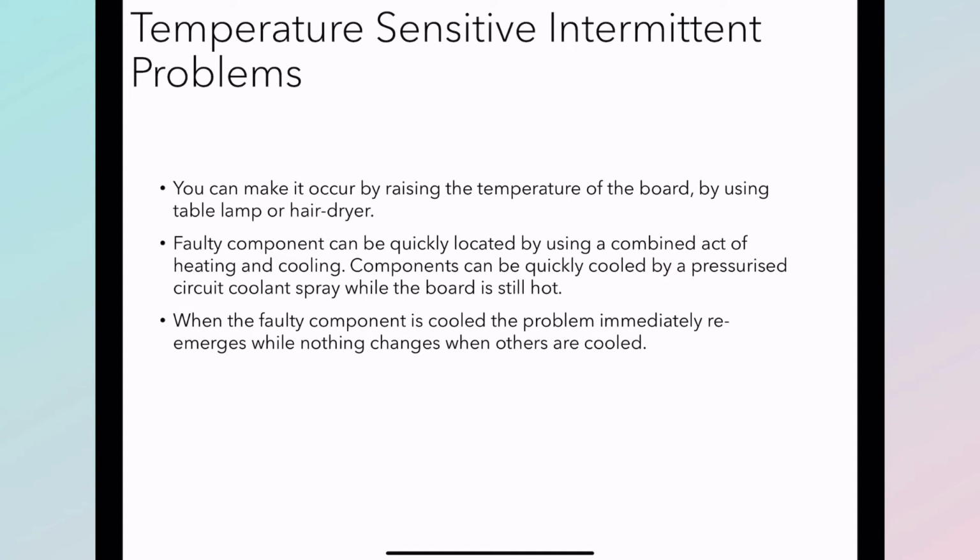Those are not difficult to locate. These can occur by raising the temperature of the board. We just use a table lamp or a hair dryer to increase the temperature of the board, and we will see the problems immediately appear.